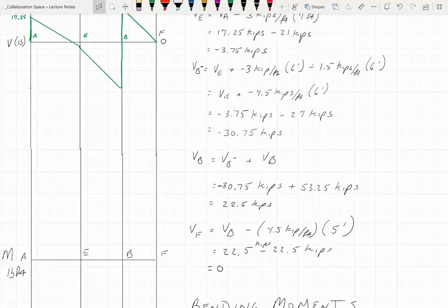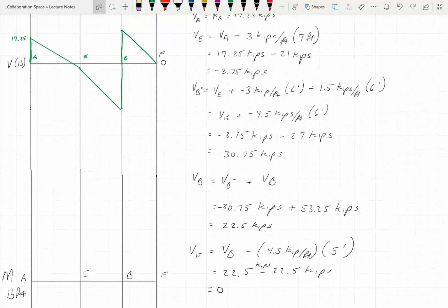But here's the interesting thing. So you remember this little gizmo here that did this bit? Yeah? Remember when that crisscrossed the line at 0 in the shear diagram? What did I tell you about things that cross the 0 axis in the shear diagram? Where the maximum moment is going to be. Or a moment. A max moment could be. You can have multiples. But, so, I hate to tell you this, but we kind of need a little line there too. Okay?